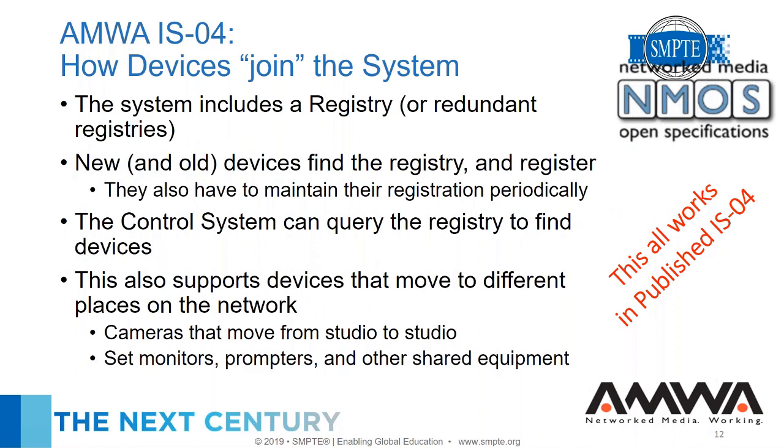The Advanced Media Workflow Association I mentioned earlier has a couple of specifications that were built in harmony with the 2110 activities. So while we were working on 2110 on Thursday mornings, we were working on IS-04 on, I think it was Wednesday mornings. IS-04 describes how devices join the system. So if I'm building, say, a control system, I need to know where all the little 2110 devices are. So in the IS-04 world, a device wakes up and it finds this registry in the network and it registers. It's really not a very complicated standard.